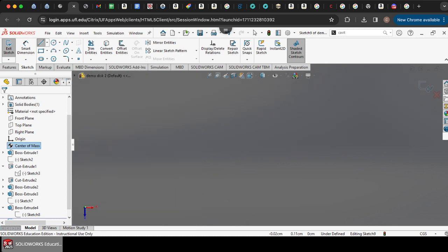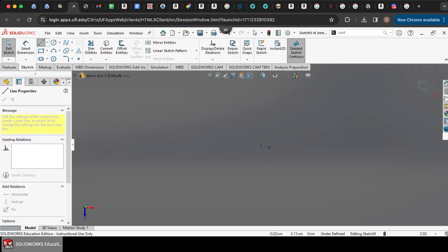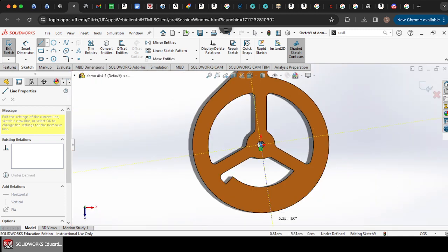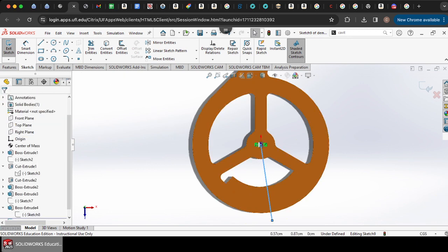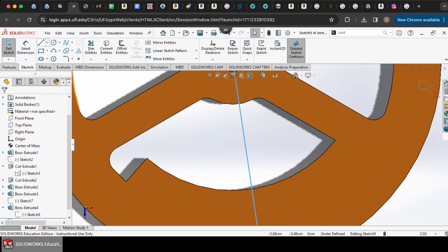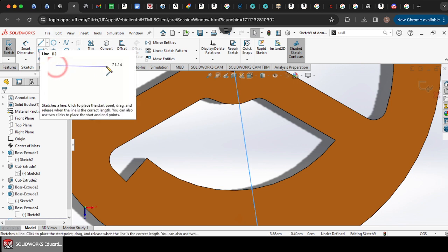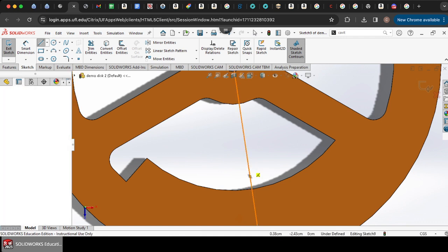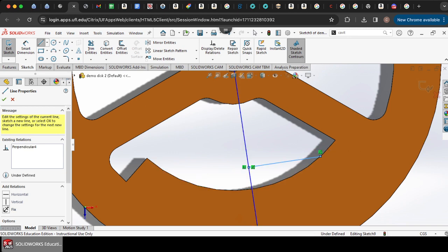Another thing that I want to bring up, while I'm zooming in here and doing stuff that you've already seen, is that the tooth of your weapon will get damaged in the fight. Whether it's you hitting or getting hit, your weapon tooth will be damaged like 100%. So your center of mass is going to change and move around at a decent speed. Not like, oh, it doesn't matter, you balance your disc because it's going to go unbalanced, but more of there's an acceptable range of how balanced your disc can be, because at a certain point it just doesn't matter after the first hit.